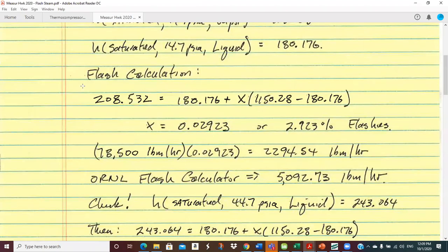You just set whatever enthalpy you have in the liquid coming in equal to the enthalpy after you drop pressure. And so the only way that can happen, because when you drop it to atmospheric pressure, it's going to drop instantly to 212 degrees, is this is the enthalpy of the liquid, plus some of this mass has to flash into the vapor state.